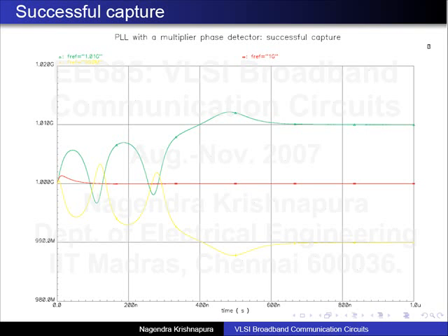Okay. Now I apply 1.01 gig. I think this PLL in fact had a loop bandwidth of about 10 megahertz. Okay. Or 20 megahertz. This is within the loop bandwidth. Okay. So you can clearly see the curve that I just described. So it will do this, and the top pulse is getting fatter, but the negative part is getting thinner. The second time the top pulse is even fatter than the first one. Okay, and the negative one is thinner. The area under that is lesser.